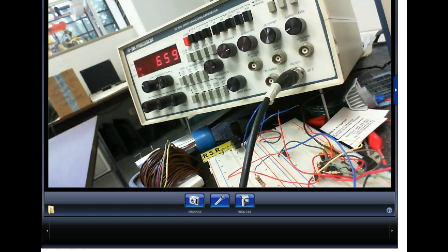The frequency counters, the function generators that y'all be able to use. This came in real handy because I got an old radio I'm working on that's having problems with the AM channels. So I can actually take this and modulate it and wrap it around the antenna. I can set the carrier frequency, and then I can dial the radio into that carrier frequency and hear the tone. It makes it really, really neat. So if you're working on stereo equipment or radio equipment, you need to be able to have that modulation, demodulate, or build your own modulator.